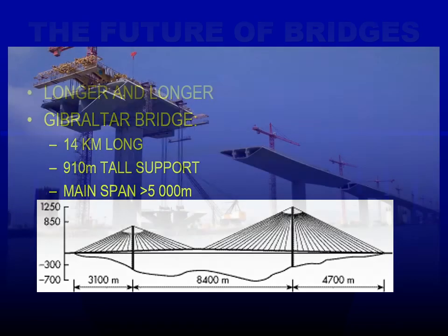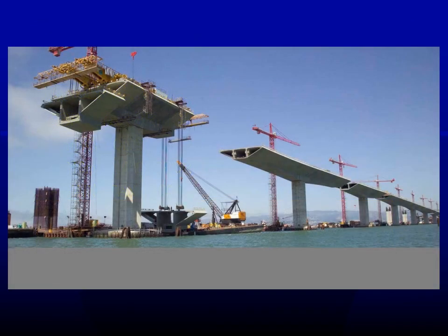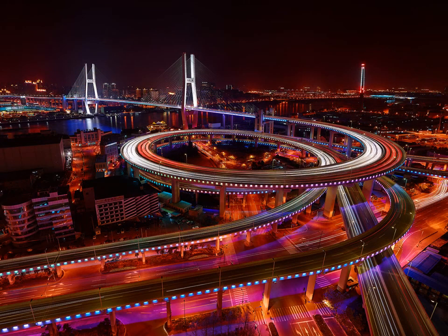But here's some other ideas of bridges. These are post-tension bridges, where elements are precast, floated to site, lifted into position, and then cables pull those elements back onto the main bridge once they're in position. Or, what about this bridge in Shanghai? It's absolutely amazing what you could create once you understand the principles around bridge building and how you can make things work.